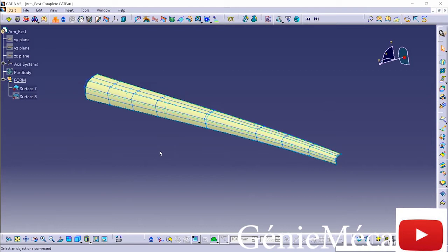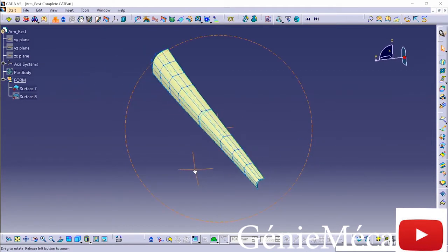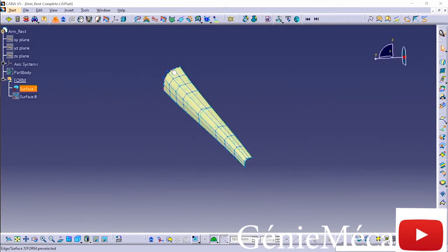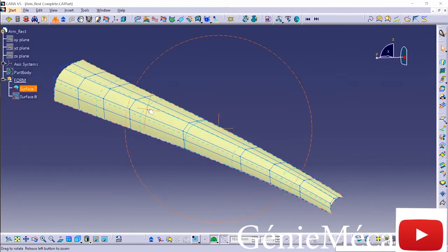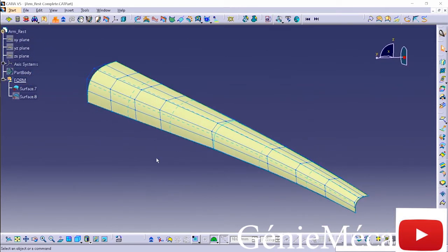Now, to relate that into a CAD system, what you see here is a surface. That surface has control points. These control points control the actual shape of that surface. This surface also happens to have an internal knot point, the solid blue line that runs through that.